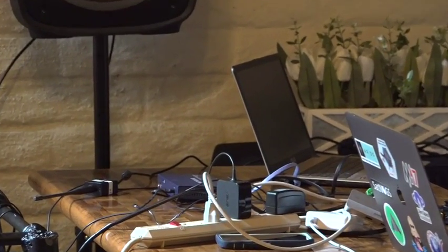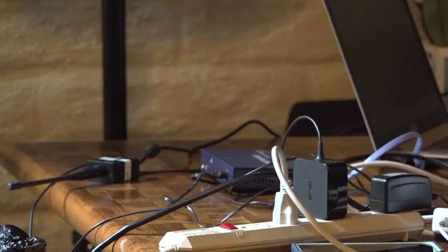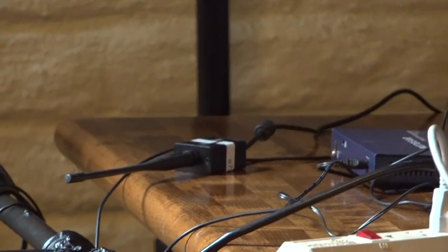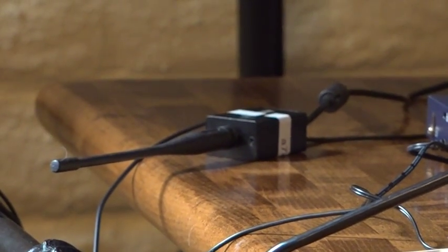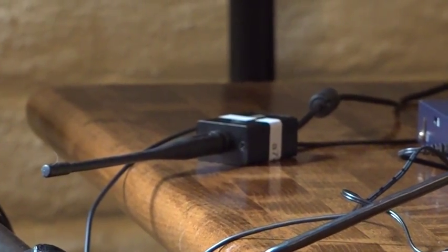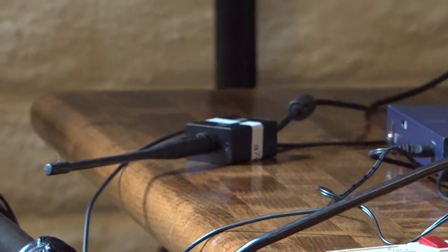The only requirement here is that whatever you want to receive will fit into the bandwidth of one of these things, and that will also control the amount of CPU power you need. As I said, I can grab 9 megahertz in about two-thirds of a Raspberry Pi 4. So the CPU usage will go up proportionally with that. And in fact, that CPU usage is constant whether or not there are any signals.